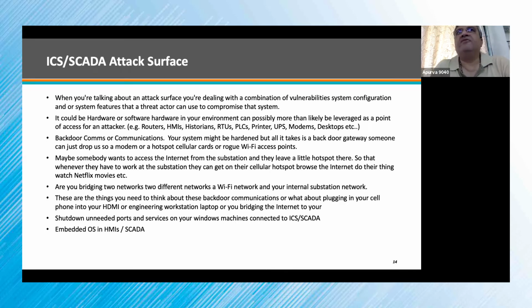Then there are backdoor communications. The OEM will always have something to look into their systems. So when you implement such a system, you need to speak to OEMs, and if they say there are things available where they need to control, then you have to see how you protect them, because these backdoors can be used by an attacker to attack your system.